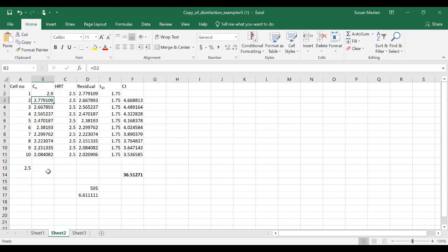Now, you're playing off the dose, which ozone is generated using corona discharge. It's electric, it's produced with high voltage. Voltage is about 15,000 volts across the dielectric. So you want to minimize the dose. So we're essentially playing off the contactor size, which is our capital cost, versus the operating costs. We can increase the hydraulic detention time further. And we're pretty close.